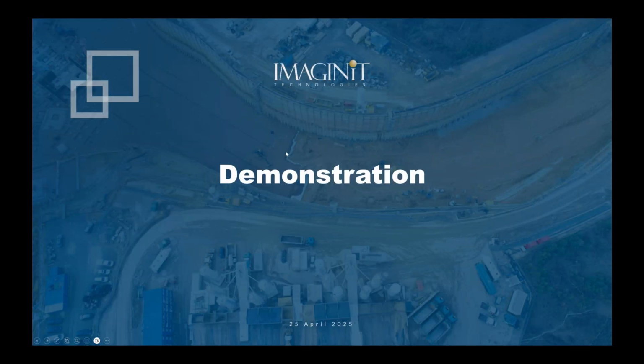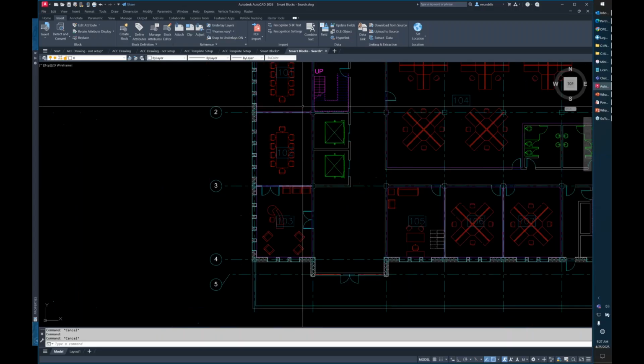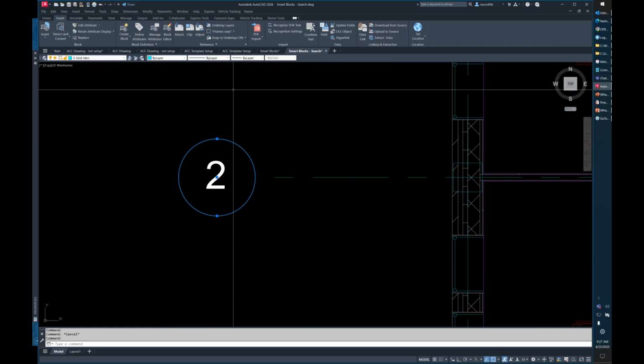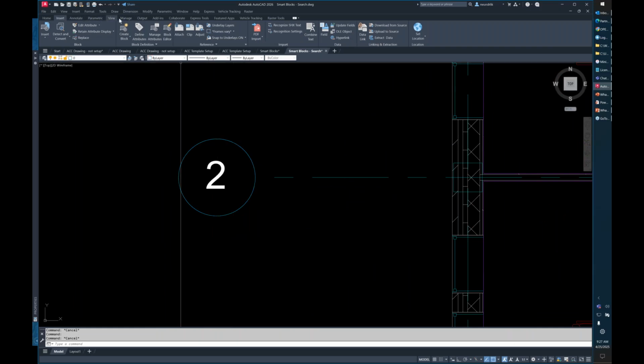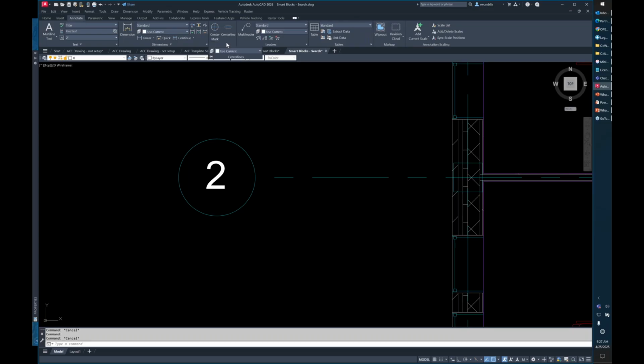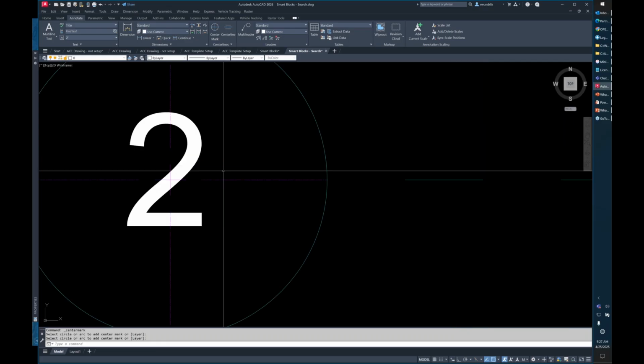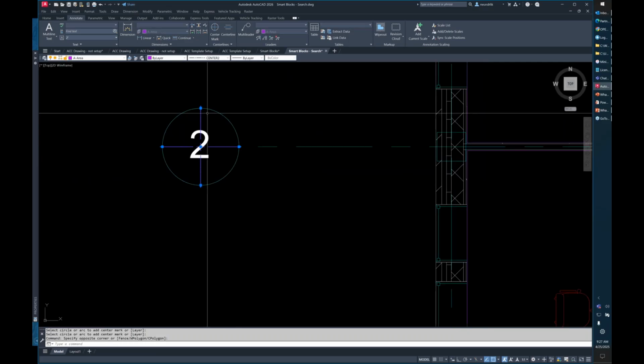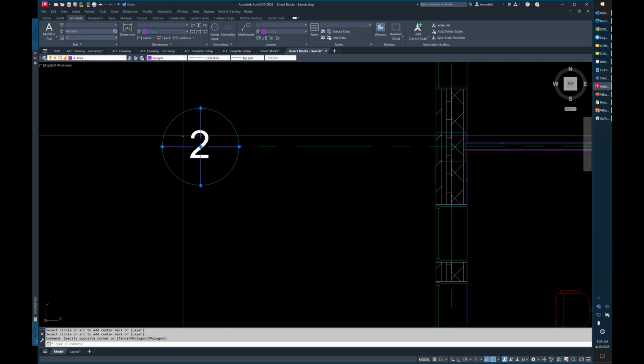So when we go back to AutoCAD, I've got a circle right here. This is an excellent one. And we go to our annotate and our center line, and I can actually specify this to use a different layer if I want. So I can go to area, center mark, pick the center mark, done. So now we have capabilities in here to put it on a specific layer. We didn't have that before.